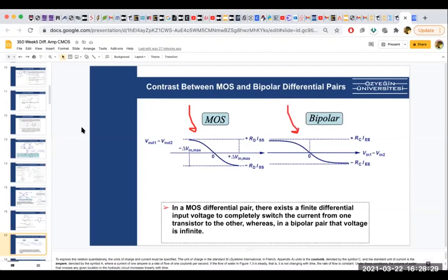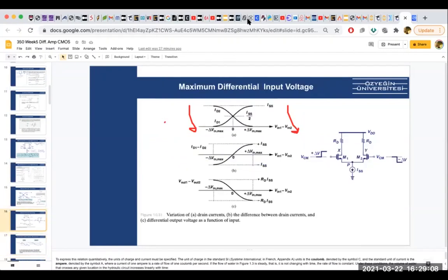Because the logic is the same, the two transistors are fighting each other, and when they have a common mode signal, they don't fight. But when they have an AC plus minus, that fight basically translates to current change. So one of the transistors, even if it is small, attracts more current, but it's the AC level that is more. The DC level is the same. So always think of it like AC and DC, right? One of them is having more current and the other one is having less current. So the DC level is always the same currents.